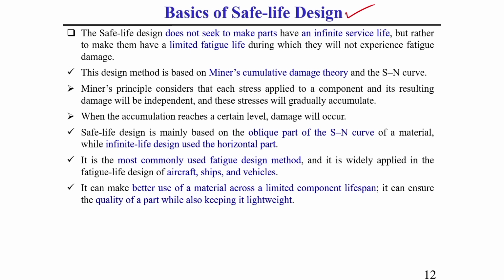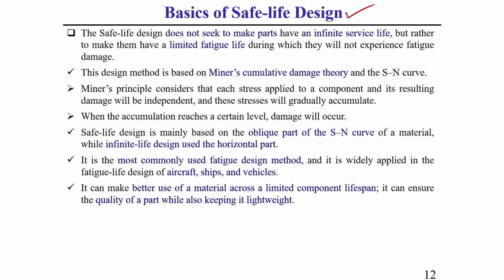In safe life design, this design method has wide applicability compared to infinite life design. The safe life design does not seek to make parts have an infinite service life, but rather to make them have a limited fatigue life during which they will not experience any fatigue damage. That means it will have a limited fatigue life, but during that span of service life, it should not be subjected to any fatigue damage. This is the criterion of this safe life design.